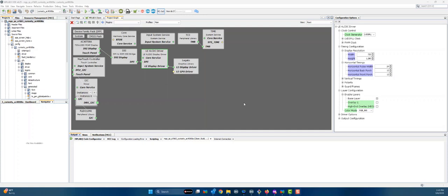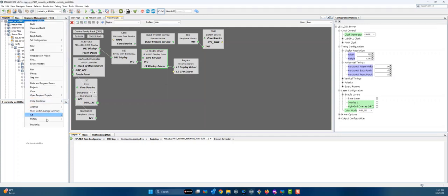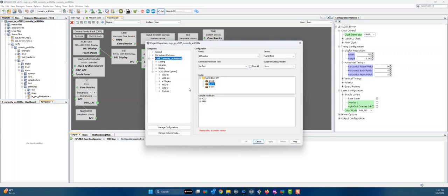All right. Now that we have regenerated the design with the changes that we made in Composer, we are ready to build it. To build for the target, the SAMA7D65, you can right-click. Let's make sure that we have set the right toolchain, and let's use the latest DFPs and the latest XC32 version.